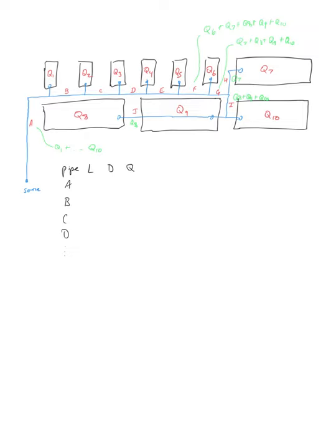I'm going to put in its flow rate. We just developed up here what the flow rates in each of those pipe segments are going to be. From Q and D, we can include a column for A if we want, and then velocity. Let's do Reynolds number. Let's do then friction factor.